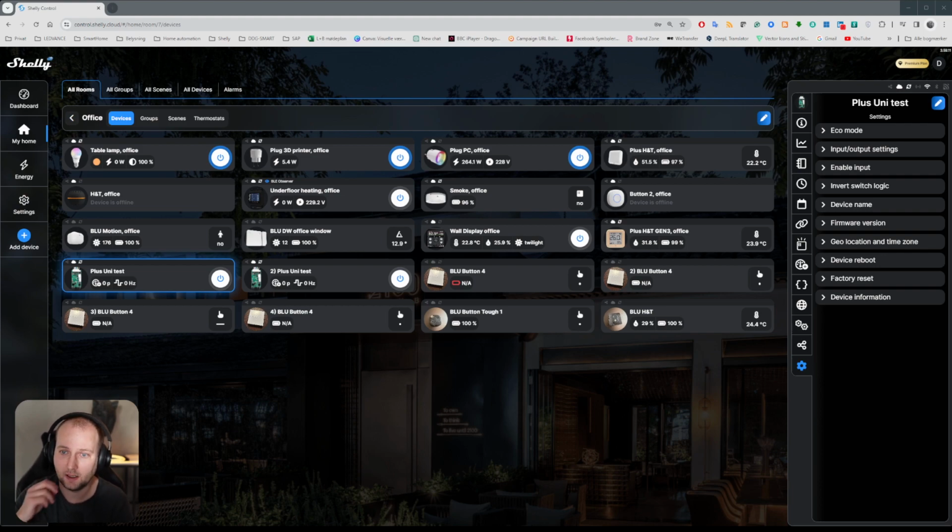Matt, I just replied to a question about the dimmer, but let me try again. To dim less than 10 watt, you will not need a bypass. You will only need the bypass if you're not using a neutral wire. If you connect the neutral wire to the dimmer, in most cases you will be able to dim down 2 watt light bulbs or 5 watt light bulbs or even lower than that.